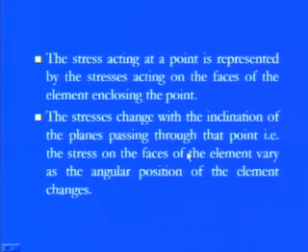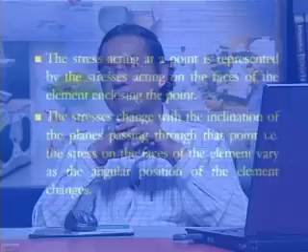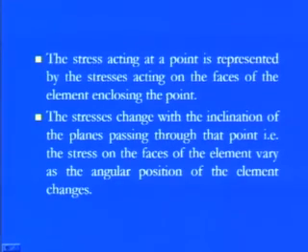So the stress acting at a point is represented by the stress acting on the faces of the element enclosing the point. That means whatever faces are there, we have to be concerned about all those stress components existing all around this plane. The stresses change with the inclination of the planes passing through that point, that is, the stress on a face of the element varies as the angular position of the element changes.